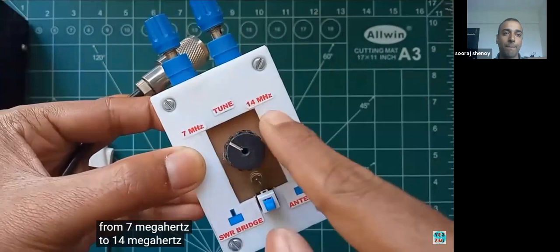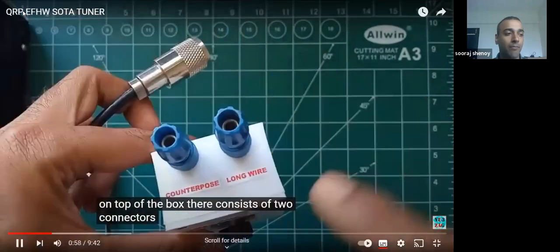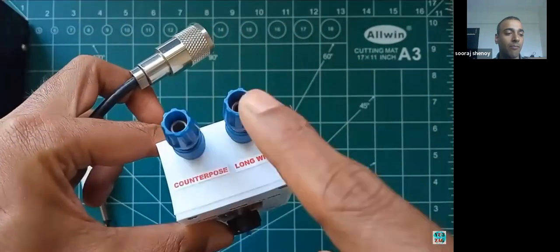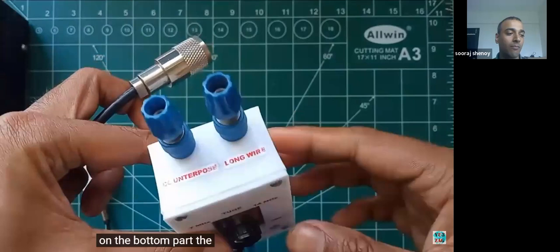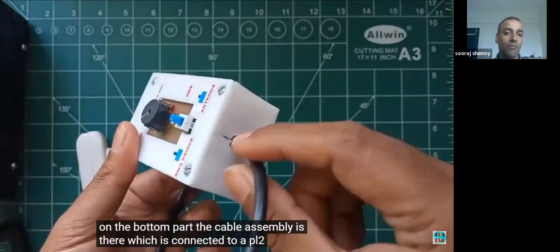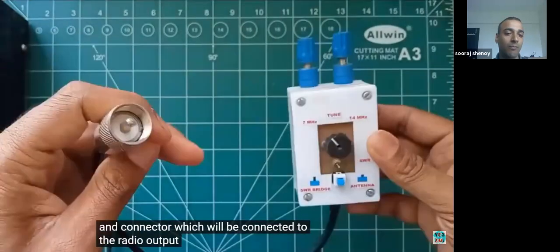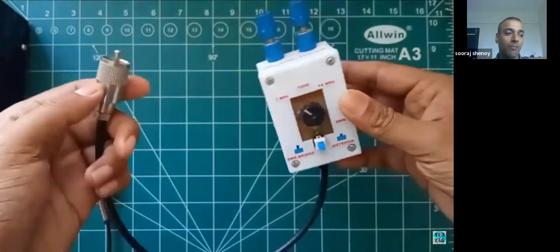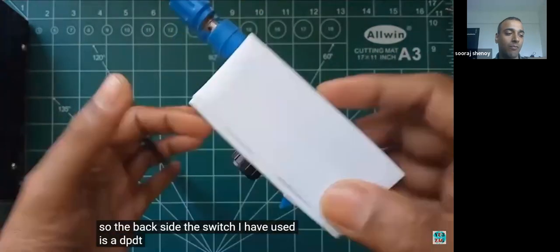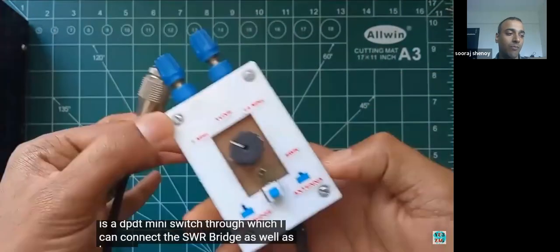On top of the box there are two connectors, one for counterpoise and one for long wire. On the bottom part the cable assembly is there, which is connected to a PL259 connector which will be connected to the radio output. On the back side, the switch I have used is a DPDT mini switch through which I can connect the SWR bridge as well as bypass the SWR bridge.